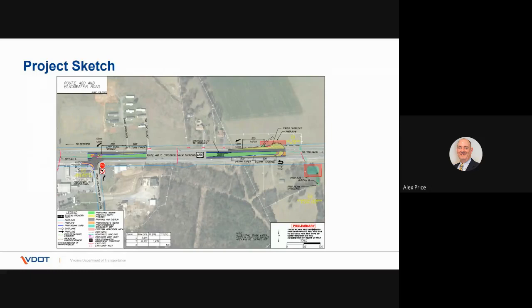A lot of times when we're constructing curb and gutter, we may need to saw cut into existing through lane pavement, maybe 1 to 2 feet, in order to form the concrete items. This requires replacing the full depth pavement and likely milling and overlay to overlap the saw cut joint or cross the entire lane.